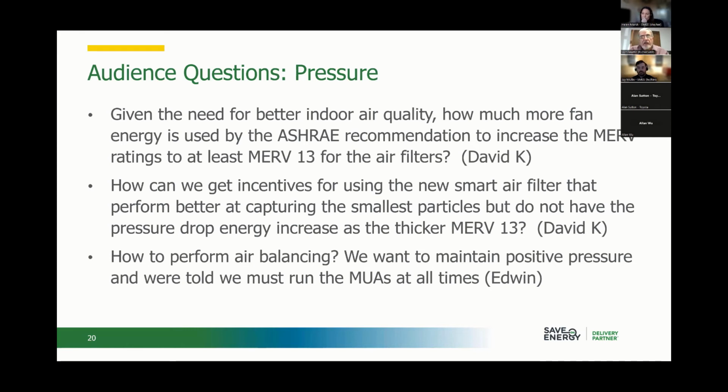And yet I've looked at a lot of air balance reports, and it's pretty rare to find somebody that actually bothers to include that number about what the fan efficiency is. Right. So I wanted to make that point. I view that as a real missed opportunity with the air balance reports.